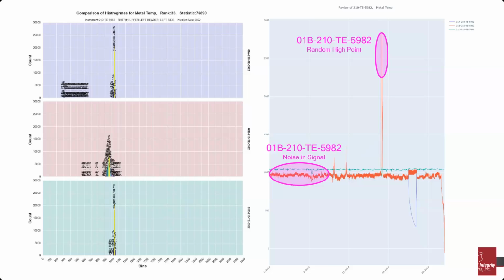Nick asks, why did the HP bypass valve, when dropping to low load, spray? Is it supposed to do that, or is something wrong? Yeah, there's definitely something wrong. These units don't require ammonia spray, and so we've been able to push the loads extremely low, and that's helping us to prevent the units from cycling. We've been able to go all the way down to 40 megawatts per combustion turbine.